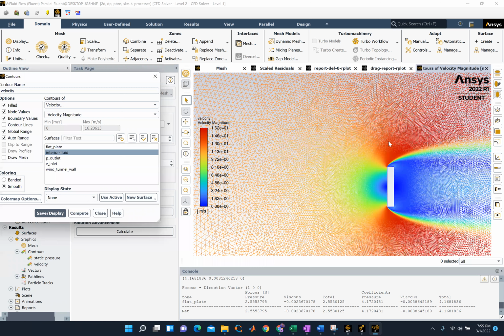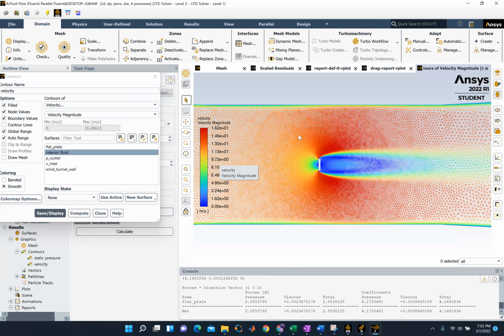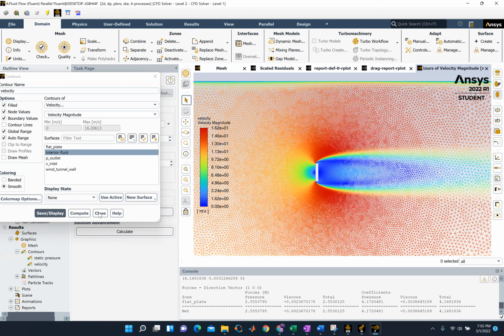This is the velocity. You can see we've got this region here. All this is zero velocity, but we've got just a little bit of velocity in here. Our free stream velocity, all this light orangish reddish stuff, is right in between the 11 and the 13. So just around 12 meters per second. And then we actually have an increase of velocity in some of these regions above what our free stream velocity is. So that's interesting to see.